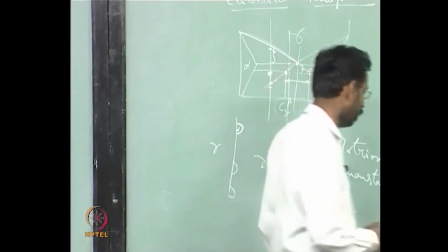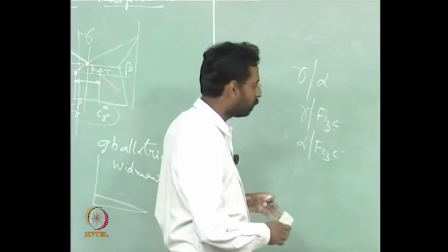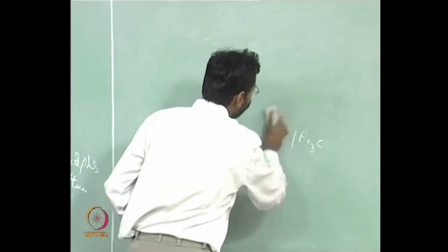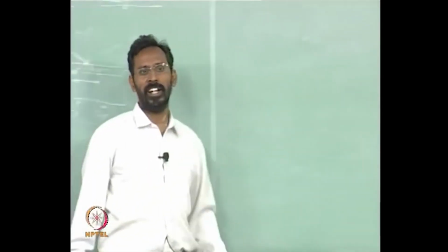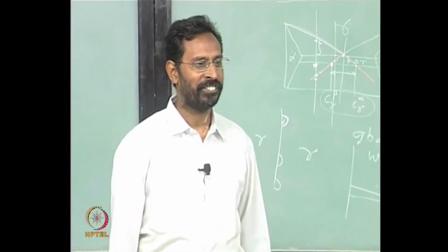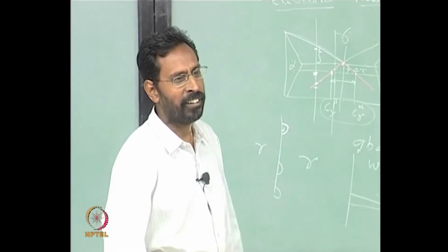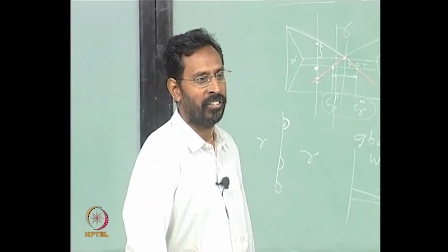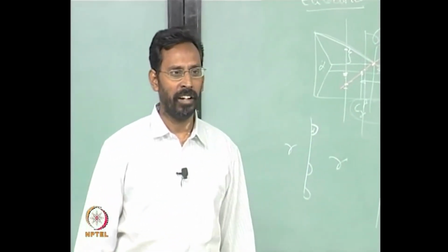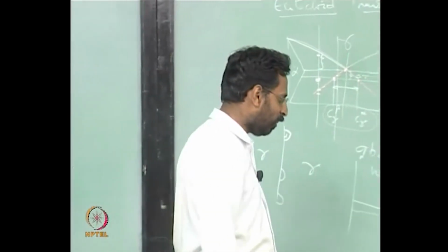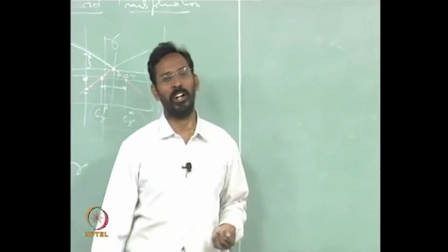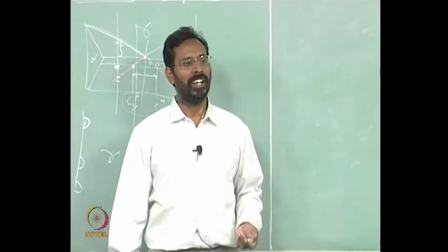Okay. Do we see a reversed eutectoid? If you want to call it a divorced eutectoid, in principle bainite is a divorced eutectoid, is it not? There is no lamellar structure. So it depends on where you are having the, actually interesting question. We do not actually call it eutectoid because it is not happening.